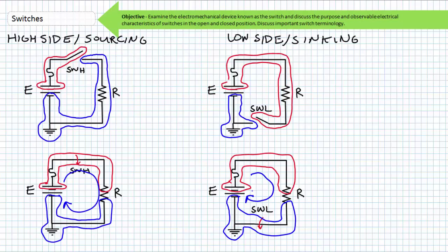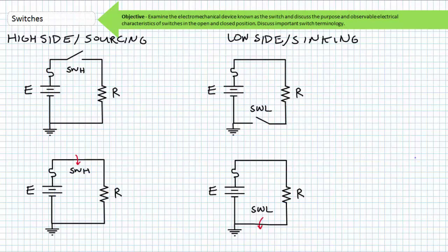Allow me to demonstrate. Consider the high-side switching arrangement. It is a series relationship of a source with an intentionally grounded negative terminal, a fuse (that's what that little squiggly S is in our schematic), a high side switch, and an electrical load.